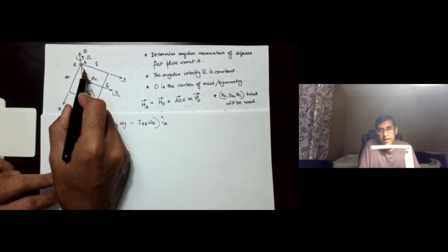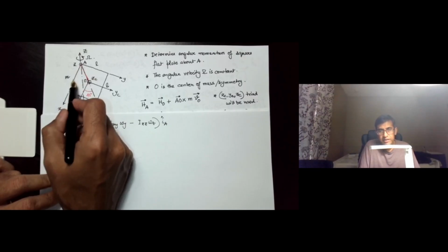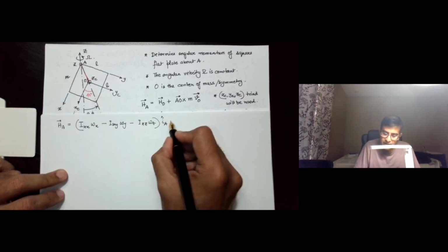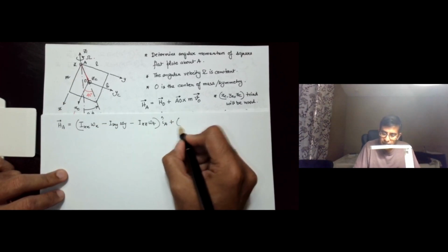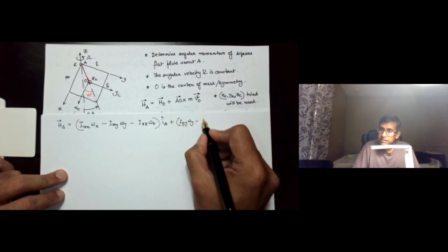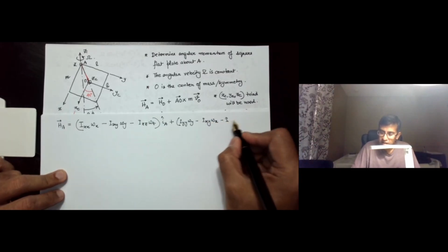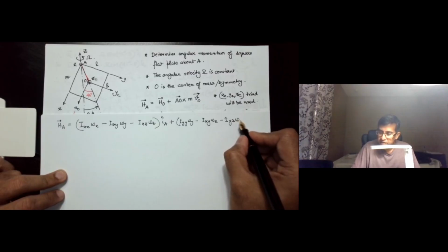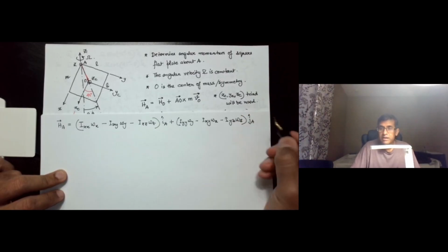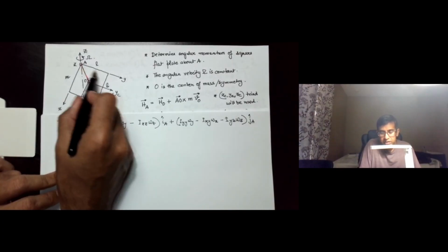So let's say that IA is the unit vector along this x-axis. Then I will have Iyy omega y minus Ixy omega x minus Iyz omega z, and this is going to be in the JA direction. So we are going to denote JA to be the unit vector along this y.